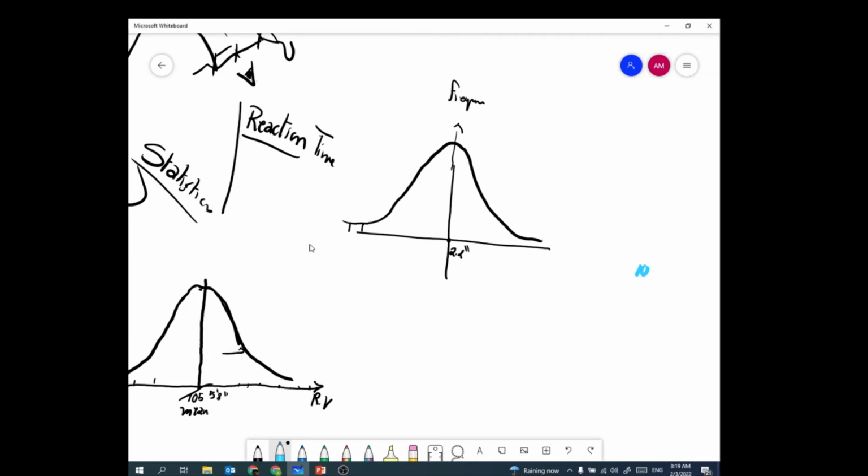So I pick something called the 85th percentile. In other words, it's the value, let's say it's 2.5, and that's the number used by Ashby. If I use this number, 85%, it's the area under this curve. Now, 85% of the people will have a reaction time of 2.5 or less. Again, 85% of the whole population of people will have a reaction time of 2.5 or less.